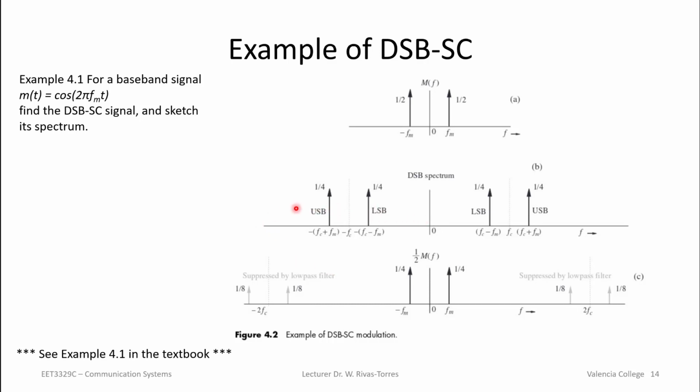Now, if we go to demodulate this signal, we should end up again with this being shifted back down to baseband. So here's our modulated signal, it gets shifted to baseband, and then it gets spread out another fc, so it ends up around 2fc.